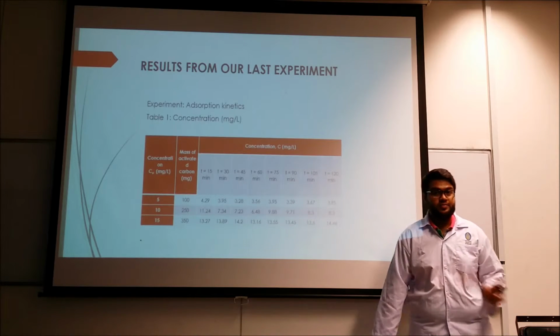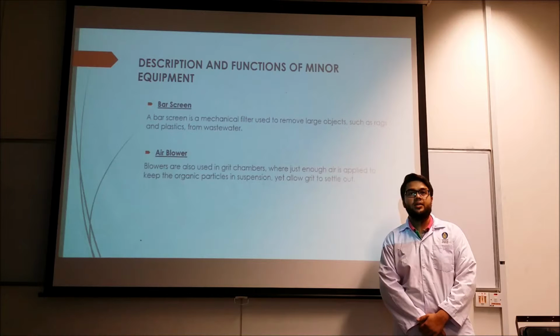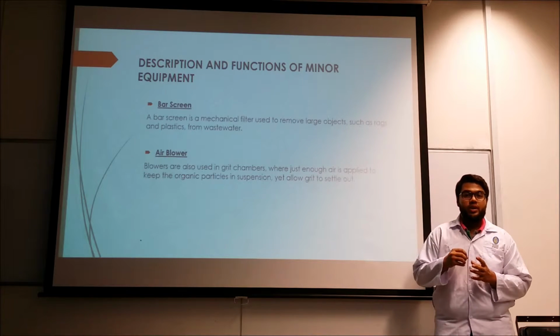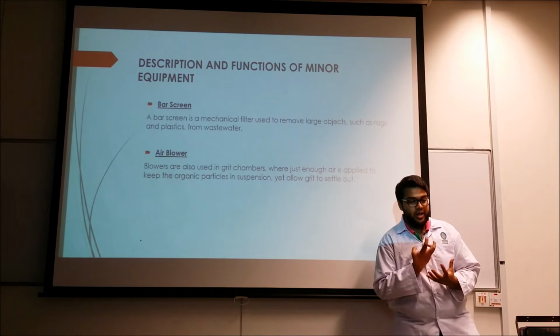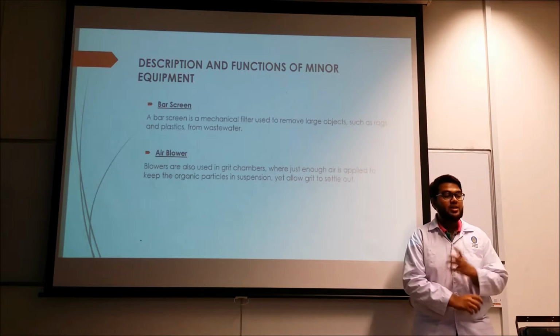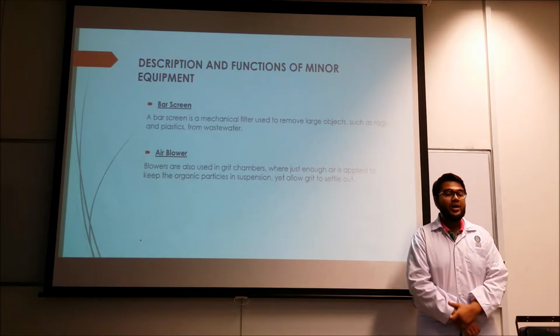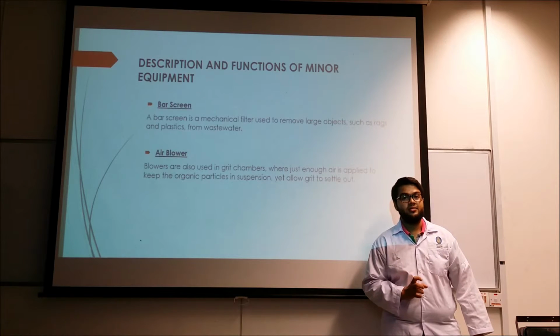An air blower. An air blower is a type of fan. It's nothing to do with the transport system. What the air blower does is that it's constructed in a grit chamber and supplies air to keep the organic particles in suspension, yet allow the grit to settle.